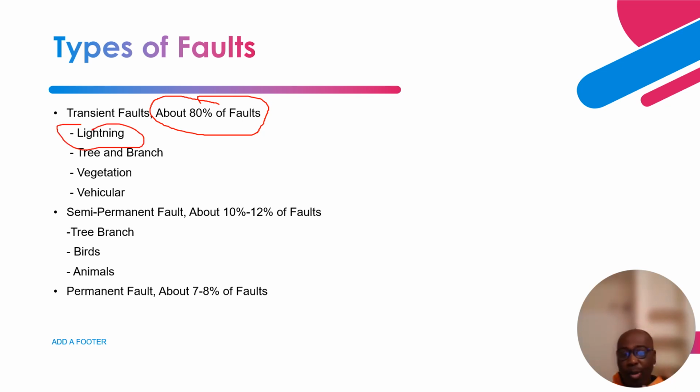So you have a distribution network, and you can have a lightning strike on the phase conductor, right? Basically the fault ionizes the air and it disappears. So transient faults are very temporary faults. You can also have a tree branch fall on the distribution feeders, and basically temporarily, and then fall off.